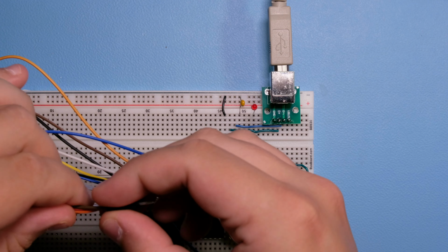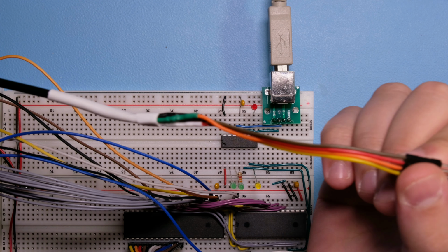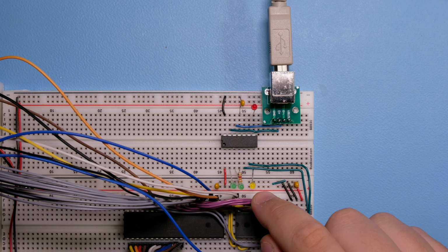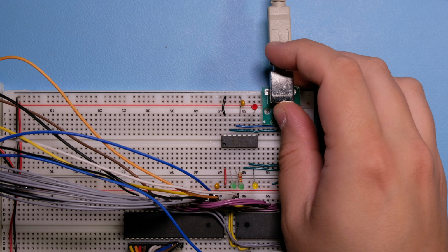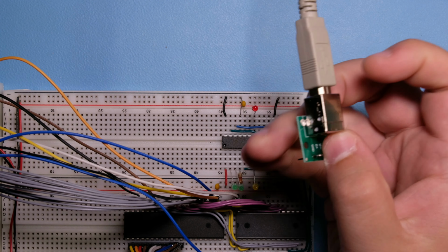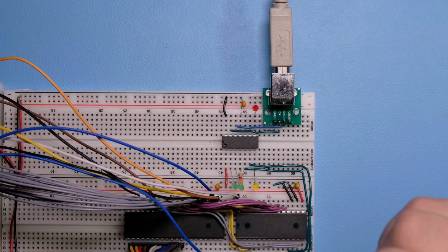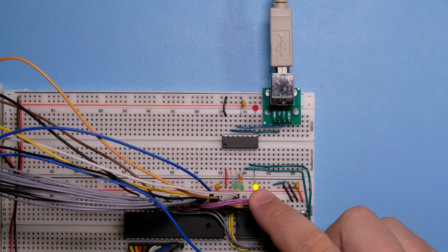Alright, so I had a hunch that maybe it was my janky cable here. That was the reason for not being able to configure the USB device. And so I went ahead and I got this little USB-B breakout board. So you have the V-bus, D-, D+, and ground broken out on a breadboard friendly header. And wouldn't you know it, but now it works. So if I turn on the power to the computer, you'll see that the device gets configured.